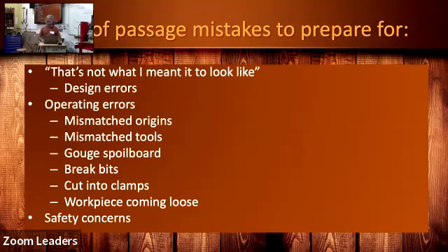Dave talked about what happens if you mismatch your origins. Let's say you told the design software it's the top of the workpiece, and then when you set up Mach, you said, no, I meant the bottom of the workpiece. You're going to drill a hole in your spoil board. It happens. You picked the wrong tool.